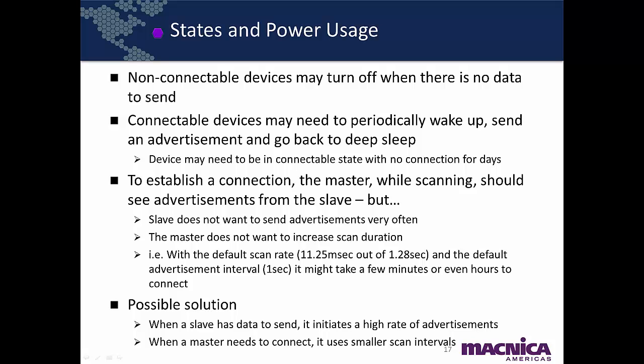Now, this leads to a timing issue between the peripheral and the central, advertising and scanning. To save power, the slave does not want to be sending advertising events too often, burning valuable battery power. And the master does not want to be scanning all the time either.